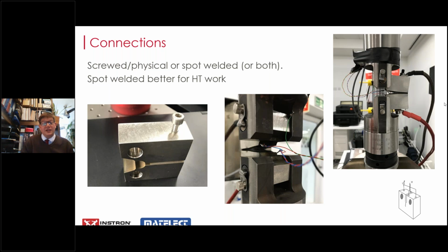For the signal connections, getting highly localized points is also important. Again, screw fasteners can be used. As a general rule, we recommend that the screw fastener has an insulated washer just before the specimen. By doing this, you define the connection point as immediately underneath the screw and not any of the surface which is being crushed against the specimen.